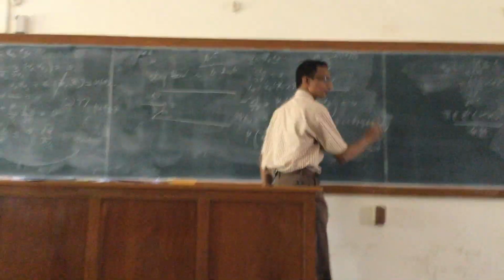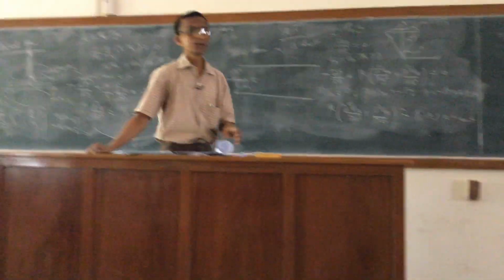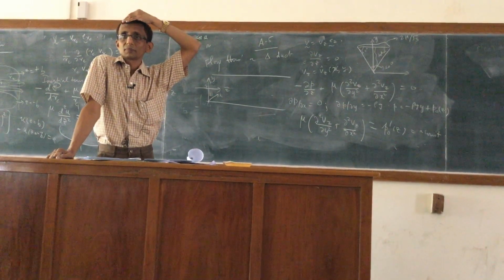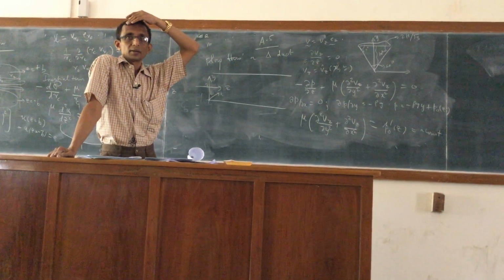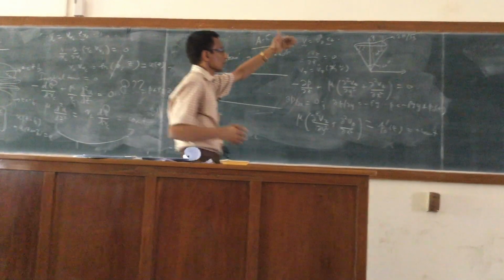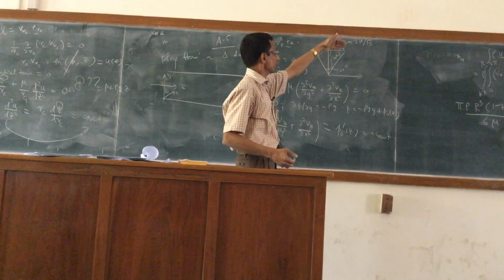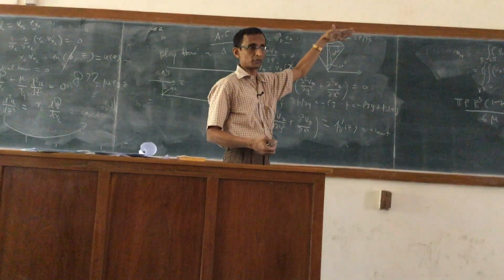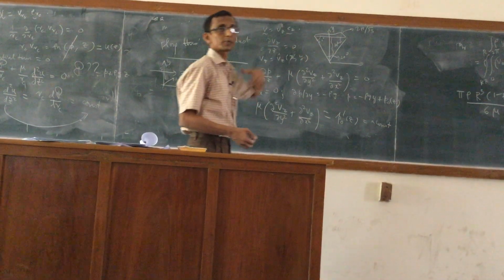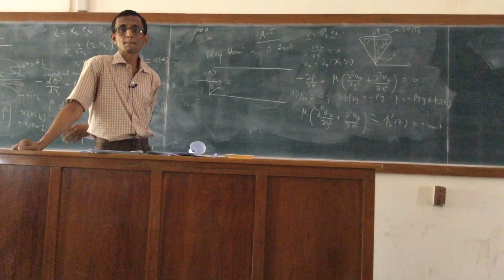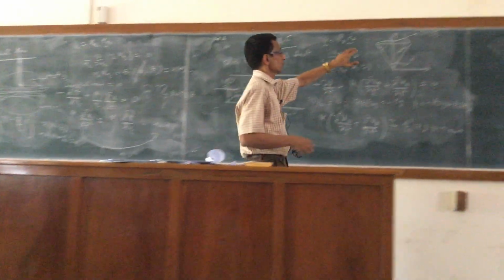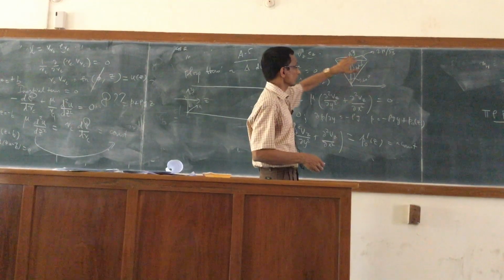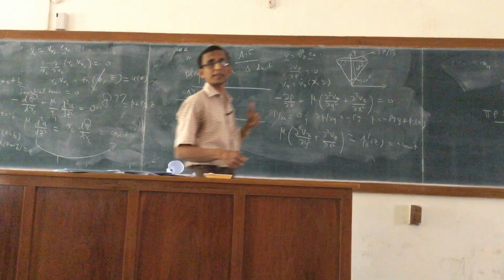But now the solution of the problem is made difficult by the no-slip boundary conditions, right? So you would have to imagine the solid surface is both inclined as well as on top, and the fluid is flowing in between, right? So what would the no-slip boundary conditions be? So y is equal to h on the top surface and all along the inclined faces, right?